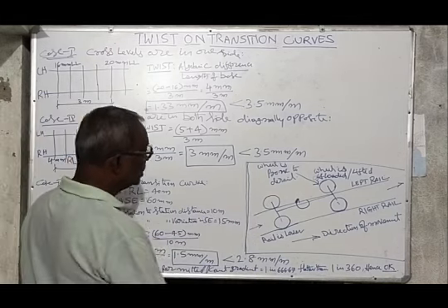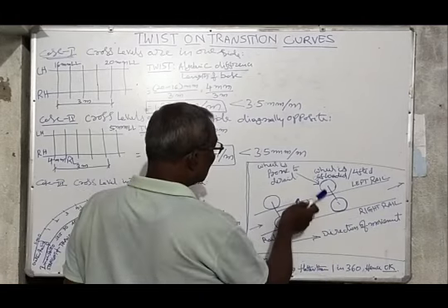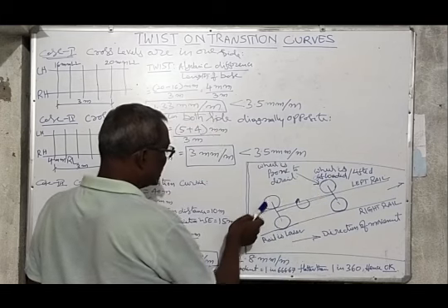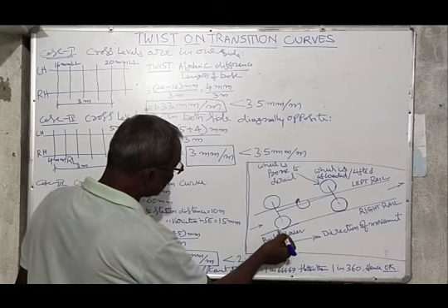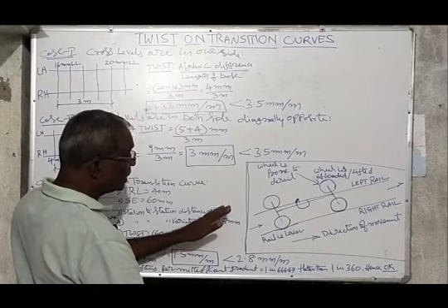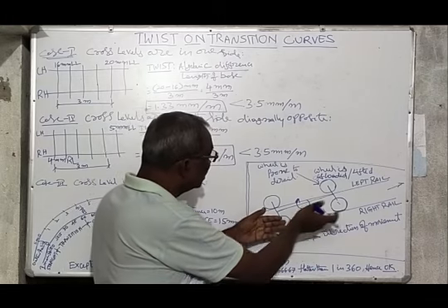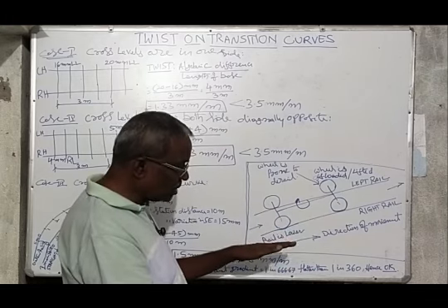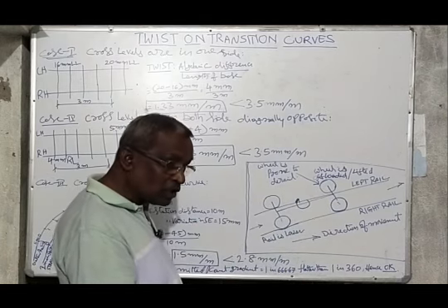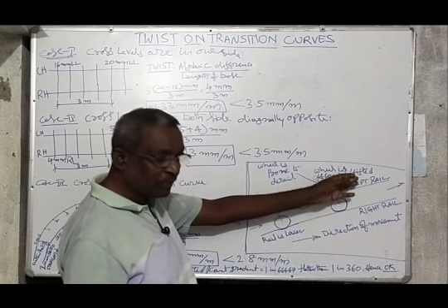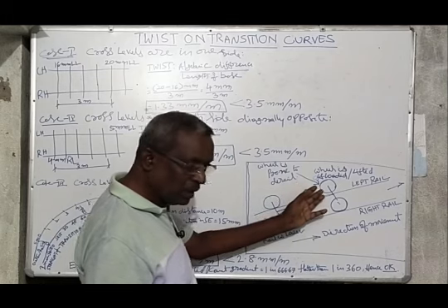Similarly, here also, this is the left side rail, this is the right side rail, this is the direction of movement, this is the front wheel set, this is the rear wheel set. While moving, here on the right side, one place is low. Then automatically the entire load comes on this wheel. With the rear wheel one side down, the effect is exactly opposite on the other wheel. It is offloaded, so that it is lifted. When a wheel is lifted, automatically it is prone to derail.